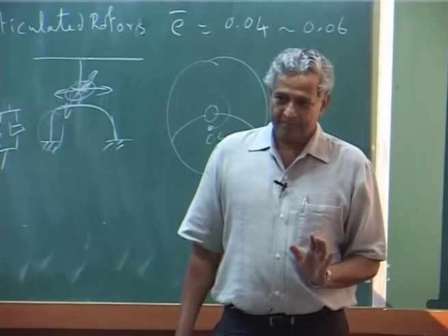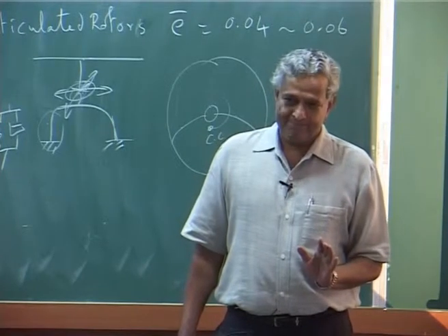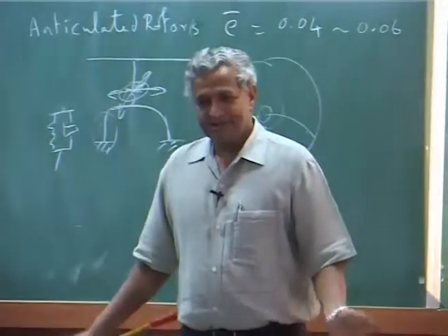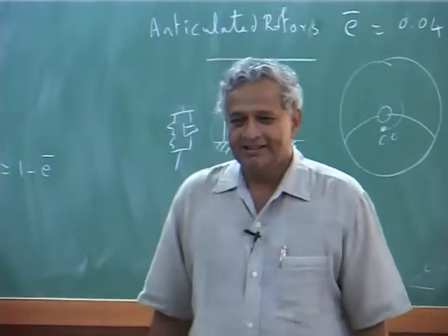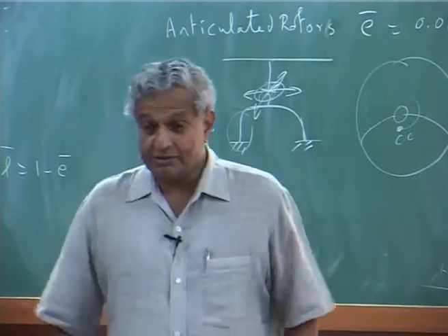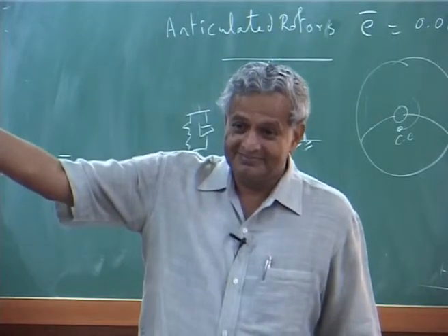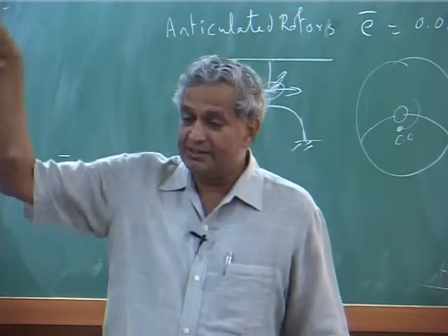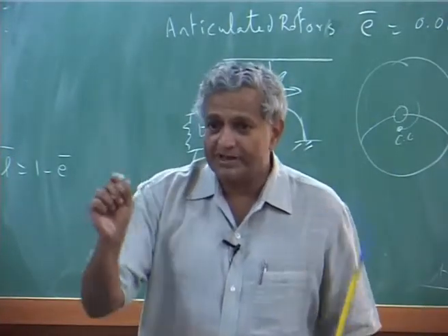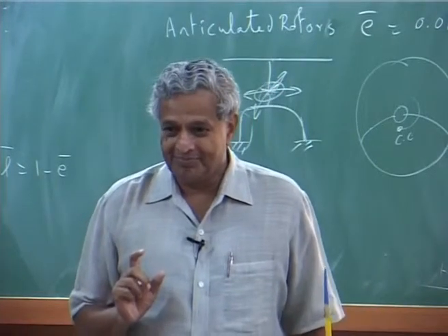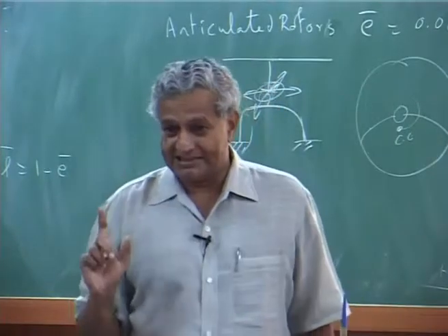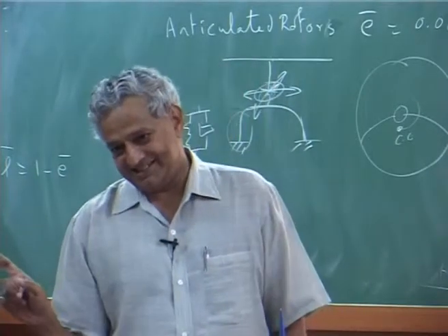And on the tail rotor we select a stiff in plane design. Yep. But then we are not much bothered about the loads which are going to come. Whatever load you say, you take it. Because the amount of load is less. The basic load itself is less, the vibratory load, so you say it is all right. Otherwise you have to put a damper there. If you want to make it soft in plane, then you may land up with some other problem. But even for stiff in plane, please understand, it is not that you make it 1.2. You have to place it far. If you make it 1.2, you are going to have instability. That instability is flap lag instability.